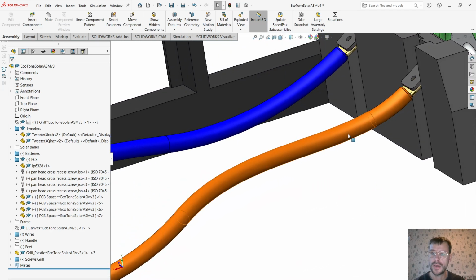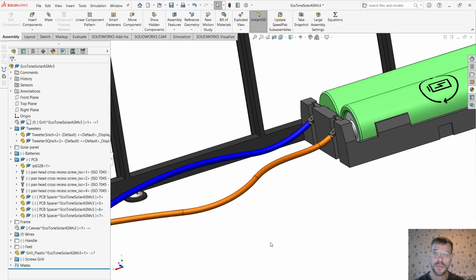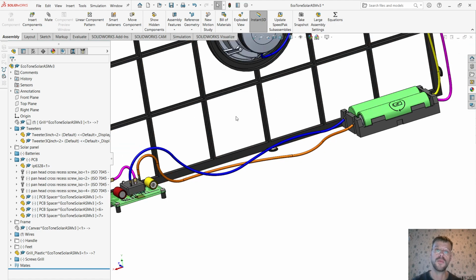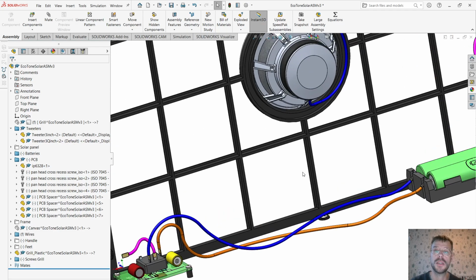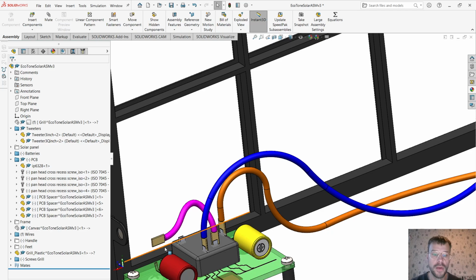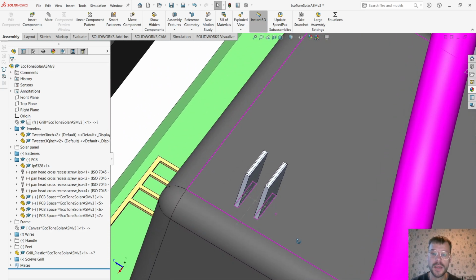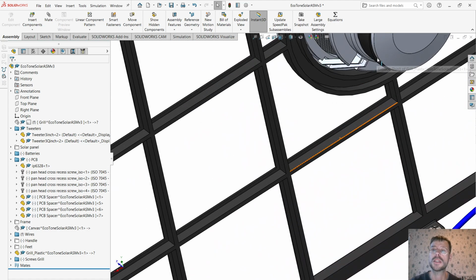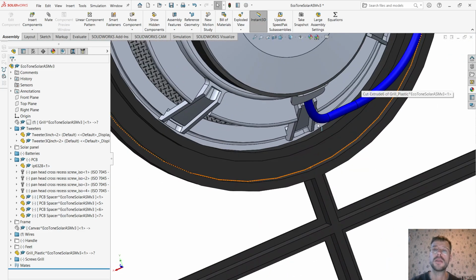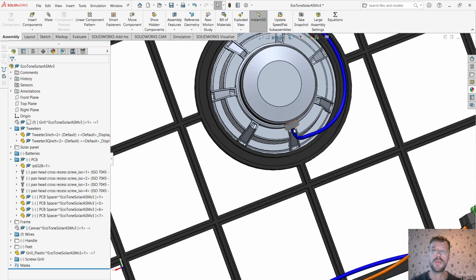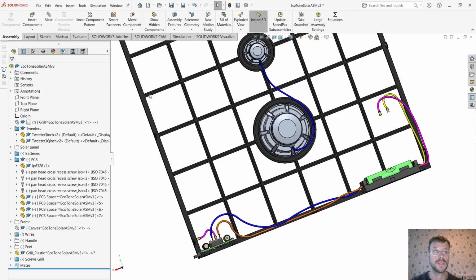They have this rubber appearance and a metal appearance up here. So this rubber thing I'll make with a 3D sketch. So how am I going to do that? First, I want to be able to see my sketches. I have one down here, center point here, and so I want the spline to go from that point to up here. Okay, so let's start by making a plane up here.